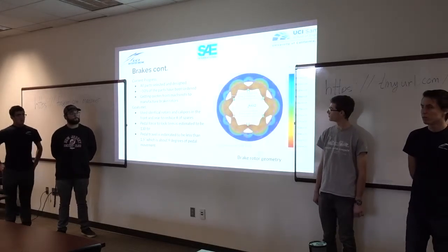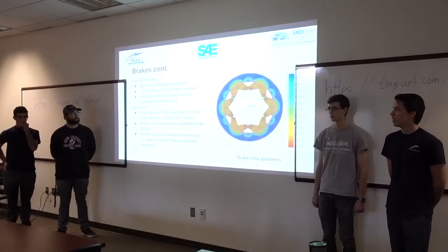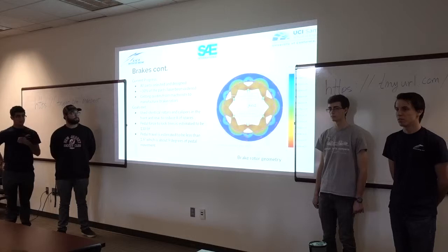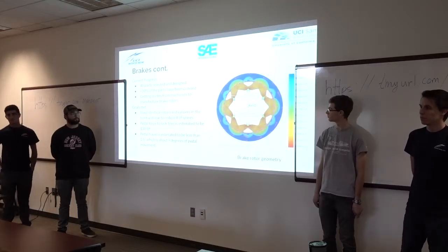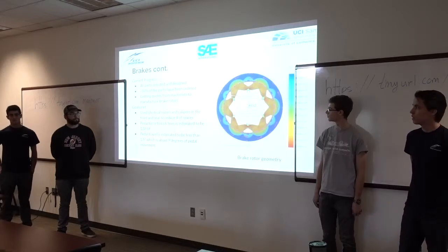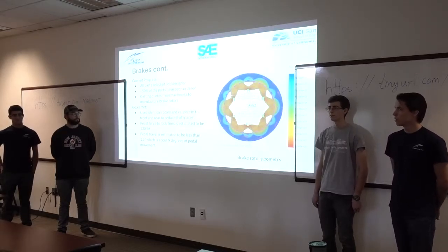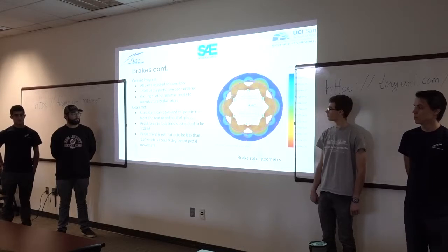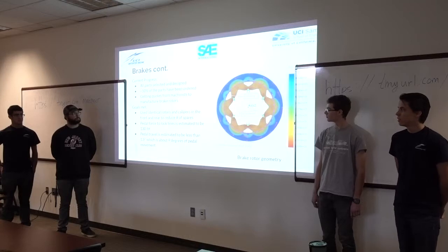So the progress for the brakes: all parts have been designed or selected, and about 50% of the parts have been ordered. The rotors will begin being manufactured within the next week. So the goals that we met were that we use identical rotors and calipers in the front and rear, which helps reduce the number of spare parts we need.